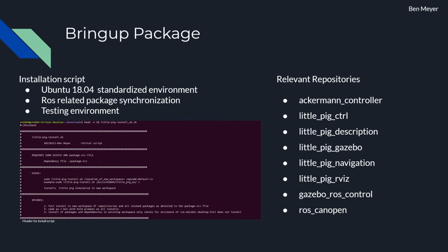Of the three main software systems that users have to interact with, Robot Operating System is the one chosen to control Little Pig, and it does this through a nodal design in which packages are passed from one node to another in order to communicate in such a way that nodes can be removed or added as needed for different functionality. Gazebo provides a testing environment in which the robot and its environment is simulated. And finally, RViz allows us to visualize sensor data in a meaningful way.